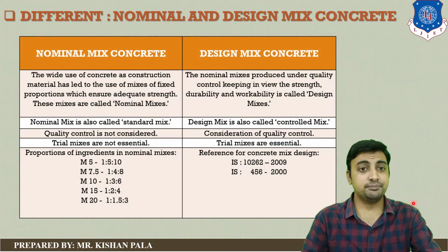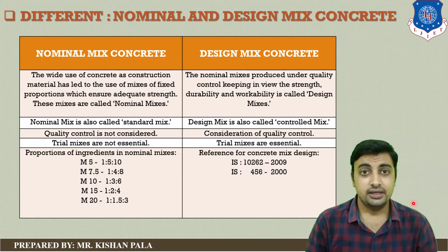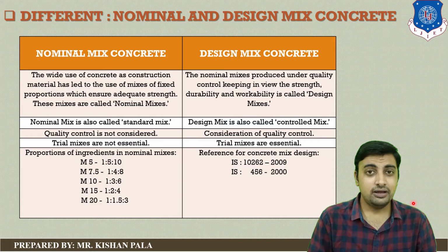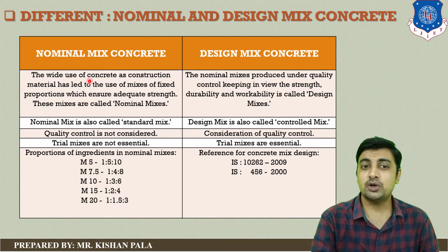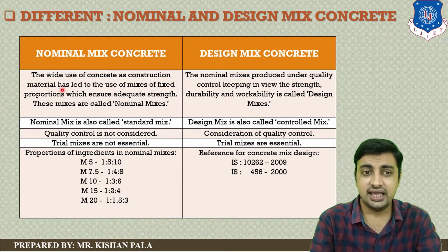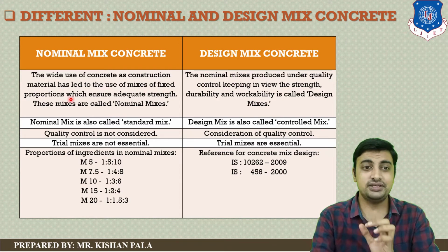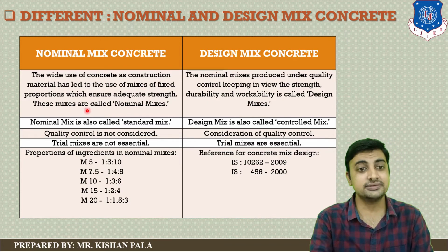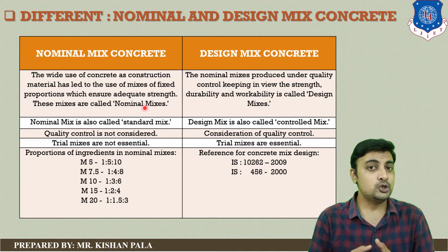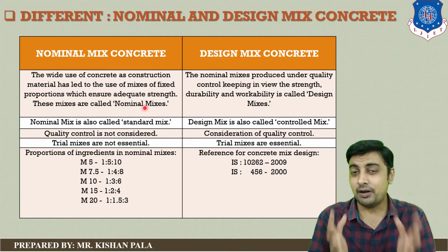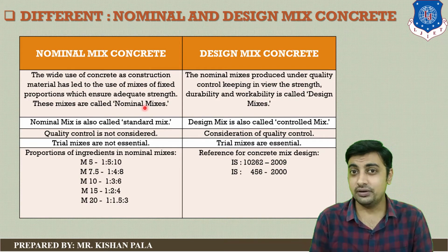Let us discuss nominal mix concrete and design mix concrete. You can see on the table on your screen, the nominal mix concrete: the wide use of concrete as construction material has led to the use of mixes of fixed proportions which ensure adequate strength, and these mixes are called nominal mix because this method is adopted to simplify and finalize the proportions of the ingredients of the concrete mass.